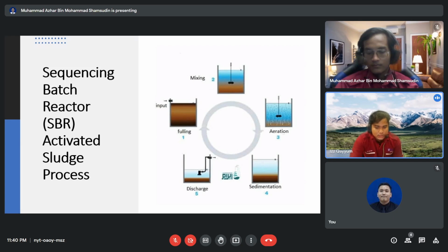The SBR process is a reform of the activated sludge process, with a new operating mode. Its operation is mainly composed of 5 processes, which are inflow, reaction, sedimentation, outflow, and standby. The SBR treatment process not only has a high removal rate of COD, but also has a high removal efficiency of color. Compared to traditional methods, using the SBR process has the following advantages. Next slide, please.